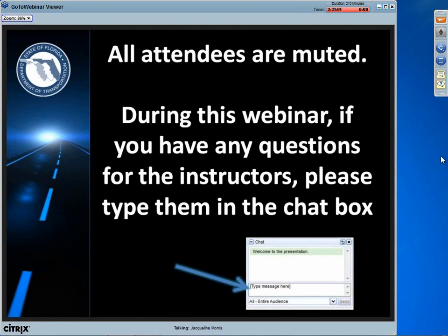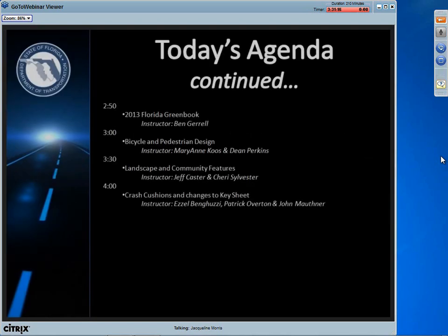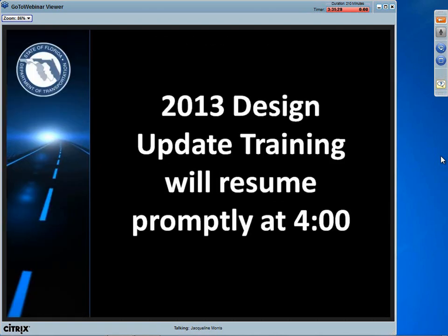And let's see, we've got 5 more minutes. Will a concrete shared use path typical be developed and included, or why not? Well, you know, you could start with index 310 and basically use the details for the concrete sidewalk, and you just make it a little bit wider. But all the details for the joints and the transitions that you would have in the sidewalk would also apply to a concrete shared use path.